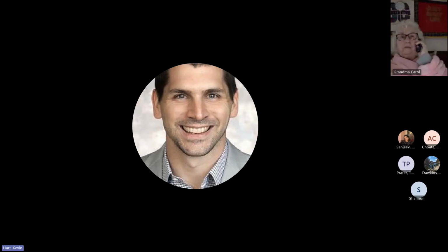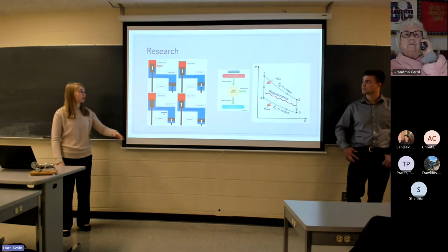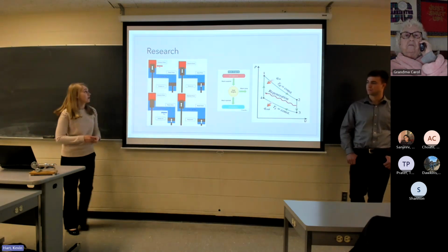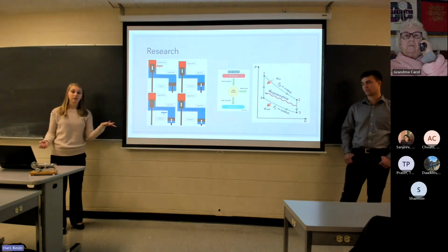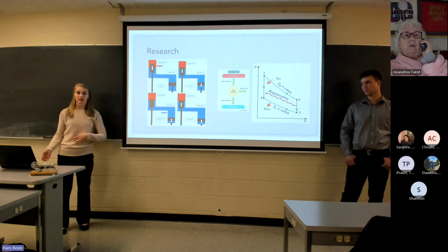as a corresponding PV diagram for it as well. So a gamma type Stirling engine has two piston cylinders. It has the displacer piston and the power piston. So from process 1 to 2 in the gamma type Stirling engine, we have isothermal heat addition.